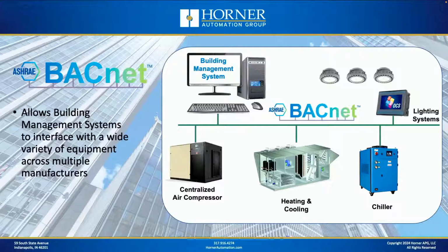Okay, so when you're looking at a BACnet system, typically what you're talking about is building management systems, where you've got a building management system that is overseeing and coordinating all kinds of different devices in a building environment. Maybe it's a single building, maybe it's a campus or a series of buildings. But BACnet systems can get rather large, and you can be talking about systems such as lighting systems and HVAC type systems, and also systems like air compressors that might be used for manufacturing or even chillers in some cases. So there's literally hundreds of different devices that could be connected on a BACnet type system.